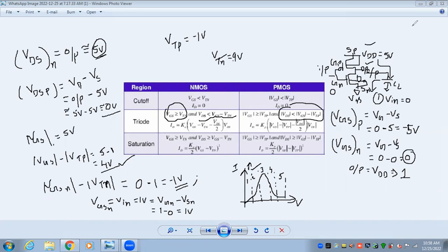Here in the right corner you see the capacitor starts discharging. Earlier it is 5 volts. Now in the first region it is 5 volts. Now it is going to start discharging. For example, we take it became as 4 volts. Okay. Now if you compare the voltages, if you write here VDS of NMOS, VD is nothing but output voltage,